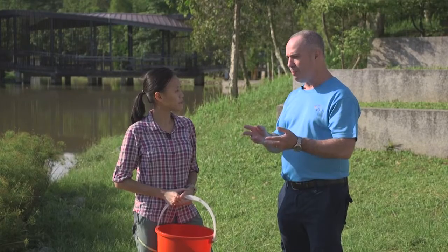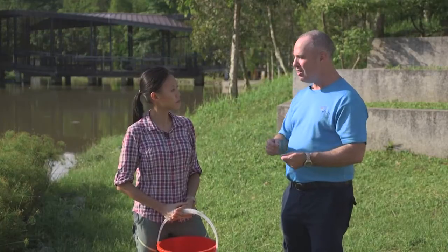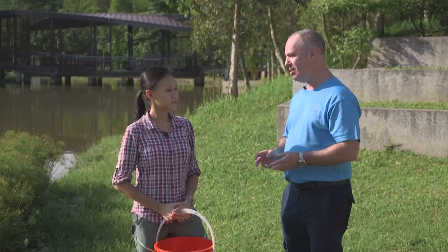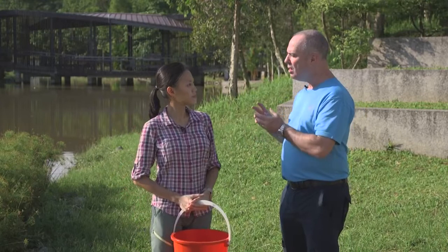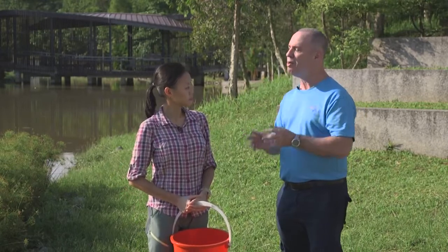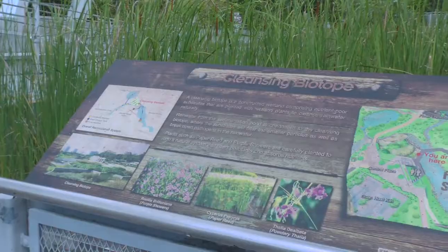And if we wanted to know something, for example, about the dissolved oxygen levels in this pond, we would have to sample every single location, every second, every minute, every hour of every day for decades and decades. And that would be impossible. So what we hope to do then is, by collecting samples in strategic locations within the pond, get some idea about the dissolved oxygen levels in the pond based on those samples collected.